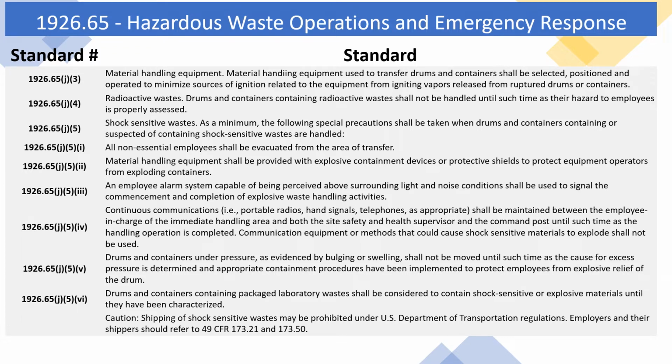Drums and containers containing packaged laboratory waste shall be considered to contain shock-sensitive or explosive materials until they have been characterized. Caution: shipping of shock-sensitive wastes may be prohibited under U.S. Department of Transportation regulations. Employers and their shippers should refer to 49 CFR 173.21 and 173.50.